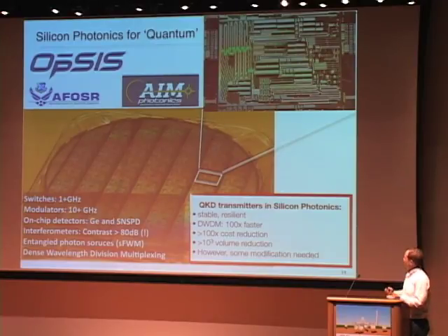And so basically, these silicon photonic circuits can be useful because not only are they stable and resilient, phase stable, you can pack tons of modulators, tons of channels on one of these chips, and so you can just scale up the key rate using wavelength division multiplexing. The cost compared to off-the-shelf commercial modulators is also quite a lot lower if you do the math. And the volume, of course, is much smaller as well.